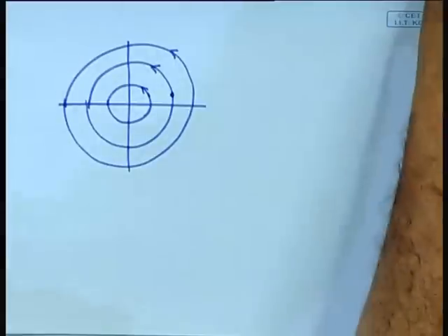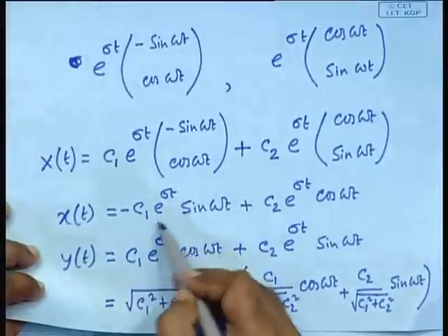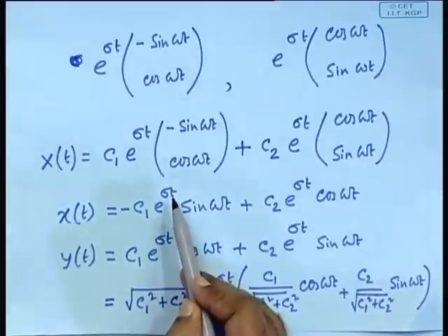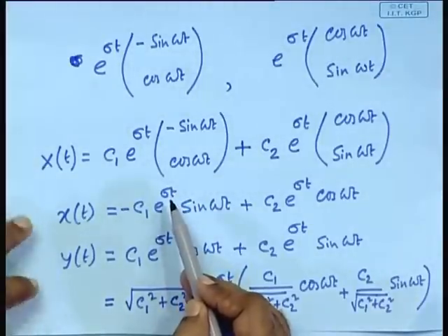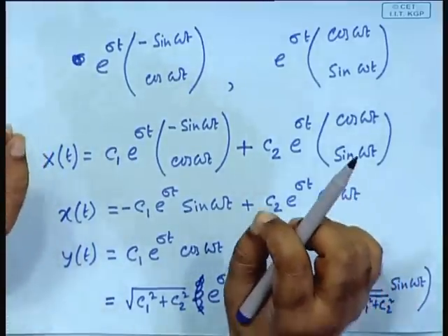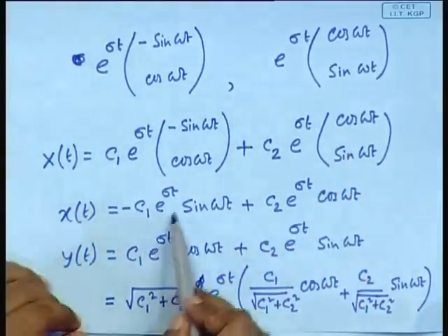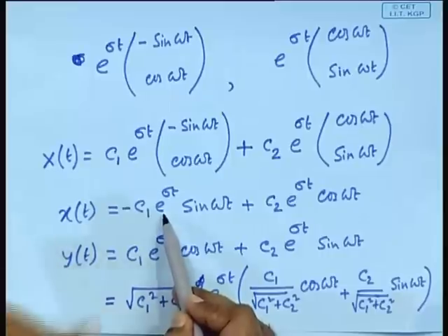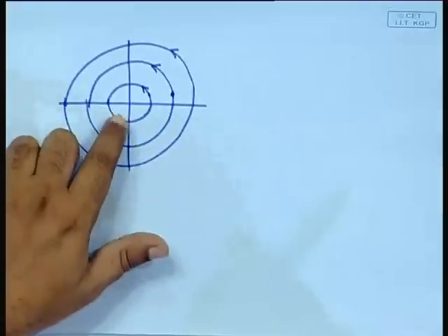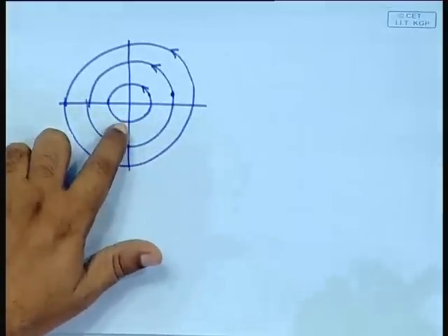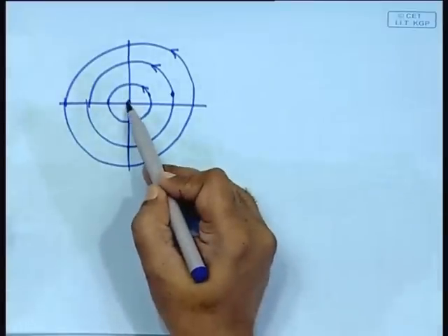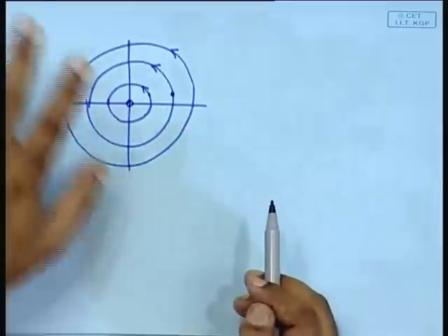The third important conclusion is, what does this term do? This term is the exponentially increasing or decaying term. So far we were considering purely imaginary eigenvalues, but now if I consider complex conjugate eigenvalues with this, then how will the behavior in the state space change? Notice that we are actually drawing the vector field around the equilibrium point, which in this case is the center.